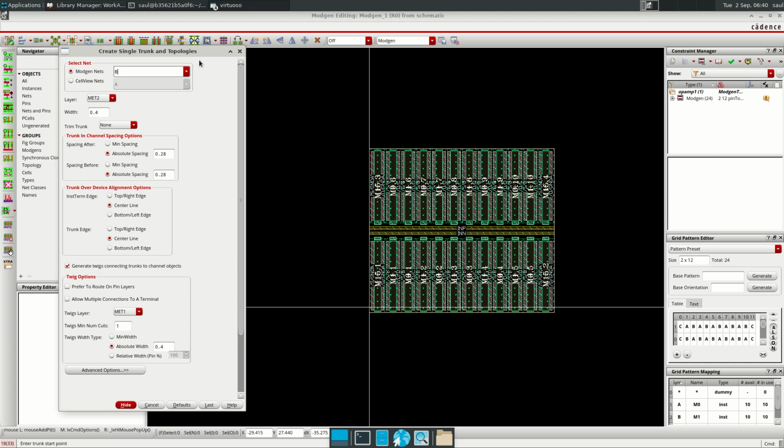In this particular case, it is 1 microamp passing through each transistor, so the totality is 2 microamps for the node B. The maximum current density for this technology, for this metallization layer, is typically around 1 milliamp per micrometer, but you have to check in the manual. So we can in principle use minimum widths, but they are not recommendable.